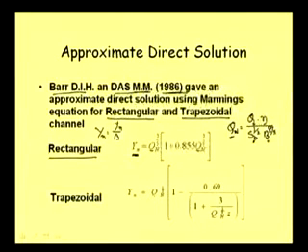Having the value of Qn, this equation states that non-dimensional depth Yn is equal to Qn to the power 3 by 5 into 1 plus 0.855 Qn to the power 3 by 5. The equation is otherwise very straightforward and not that difficult to keep in memory. So if we calculate this Qn first and then put its value here and here, we directly get the non-dimensional depth Yn.